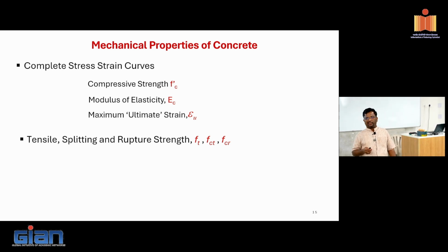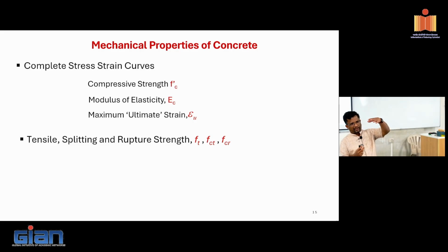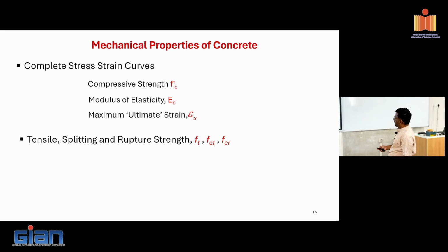It is not the true representation of the material property. If you want the actual true representation of the material, you know Saint Venant's principle: I need a material plane that is free from stress concentrations, so I need to move at least a distance d from the loading point. Ideally, for the actual material property, you need to test a cylinder or a cuboid with at least an aspect ratio of 2. Then only will you be free from the boundary condition effect.